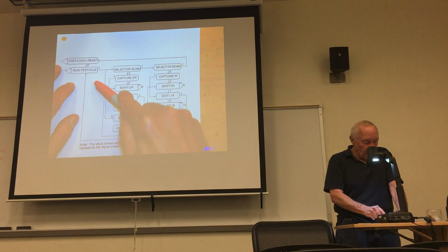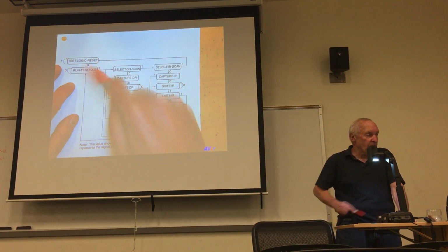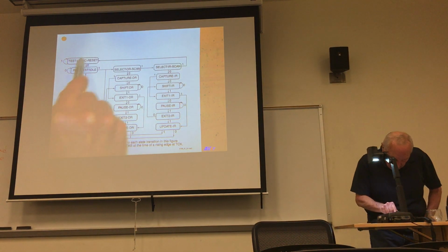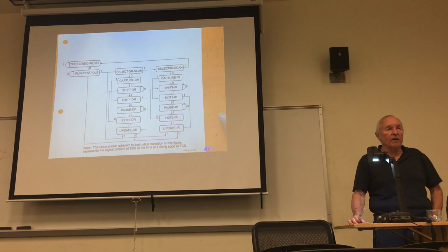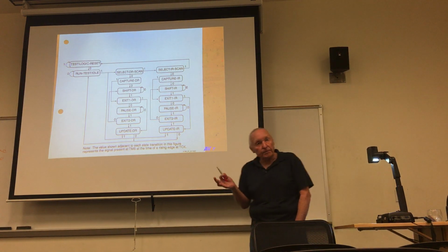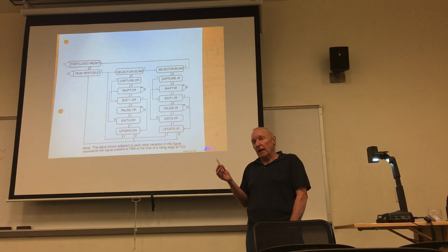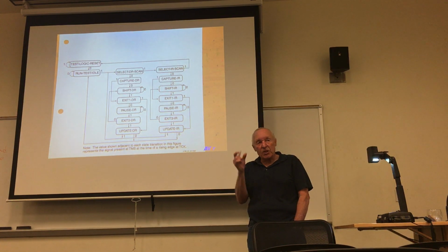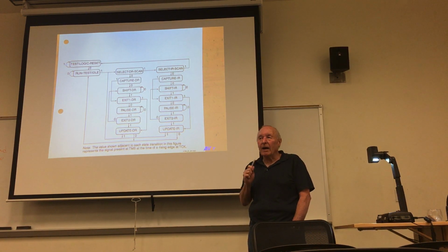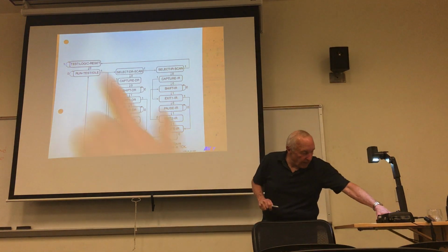You have 2 additional states, test logic reset and run test idle. Now, this test logic reset is your initial state in the finite state machine. All finite state machines, as you know, require an initial state. And normally, in a finite state machine implementation, you would have an external signal called reset or initialization that you would assert to force the finite state machine into the initial state. This uses a rather clever way of getting into that initial state.